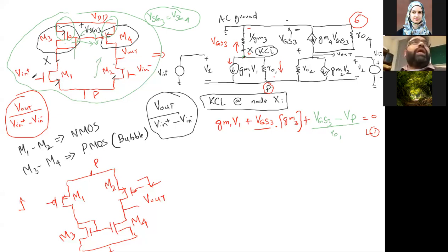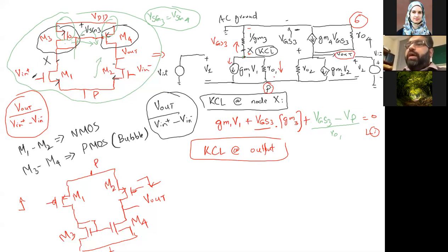Now if we want to write the KCL at the output, yeah, this is an output node. Okay? For this KCL, again, we need to write where the currents are going. We need to analyze them. So first and the most important thing, if we just see this point, again VGS3 is coming, so that's going to be VGS3 divided by, this time, R4.